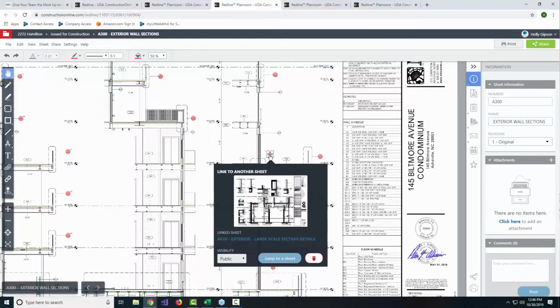Exactly. In fact, really the only effort that's going to give you the best result is the effort to just export those files out of their CAD program. Typically what will happen is when those files are exported from a CAD program, the format is usually going to be a vector PDF that really contains those additional layers of information that will give you the best results when you're looking at scanning for callouts or scanning for numbers or names.